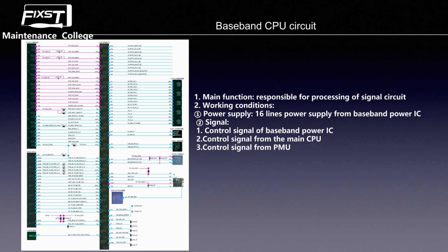Continue down, we can see the W3, this pin. This is the CPU to the baseband CPU PCIe wake up signal. And the T5, this pin is the CPU to the baseband CPU reset detect signal.